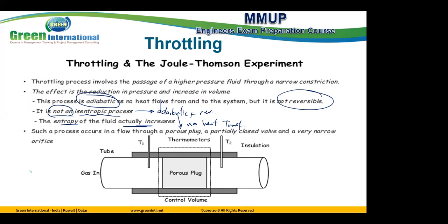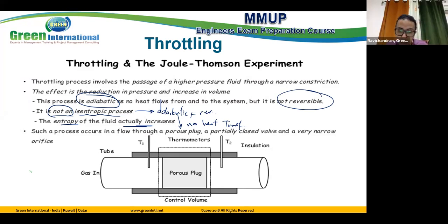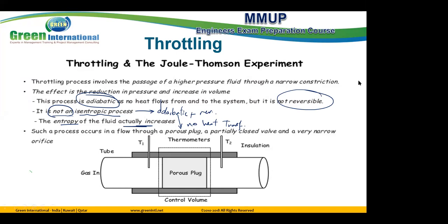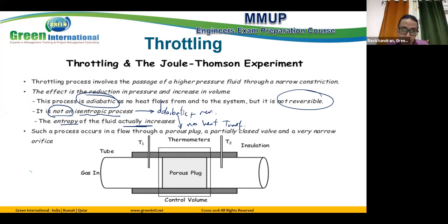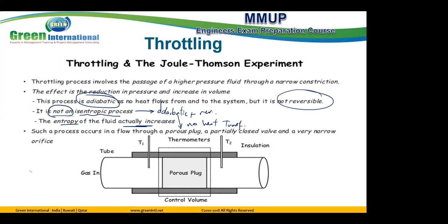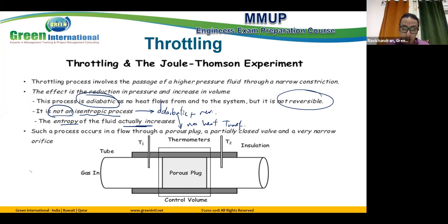Two different, okay? Reversible means state 2 comes back to state 1 again, to the original state. But actually, for this throttling process, after passing the narrow hole, if you go back, the pressure would have to increase directly, which is impossible. So it's not reversible. Isentropic means a combination of adiabatic and reversible.